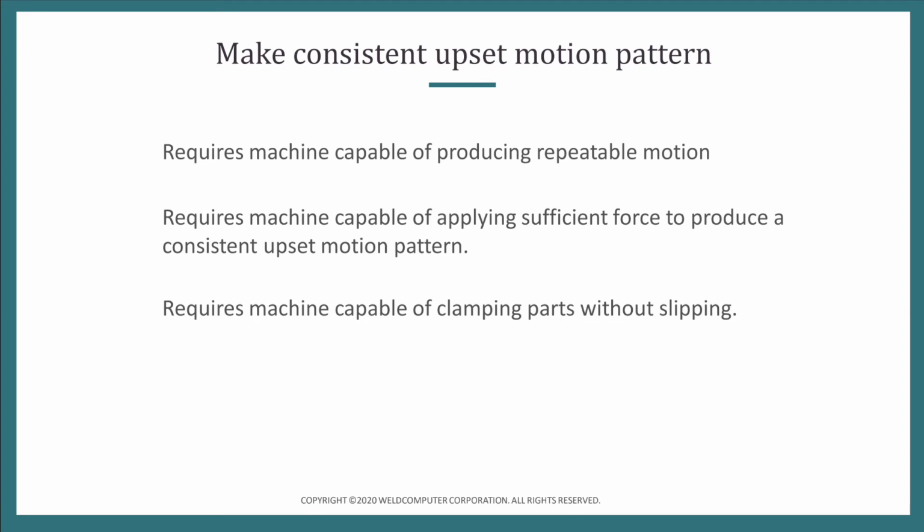So it's important to coordinate your duty cycle of applied voltage with the feed rate of the parts, and use speed control when the duty cycle isn't enough to maintain that flashing.